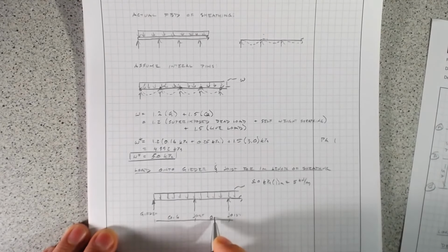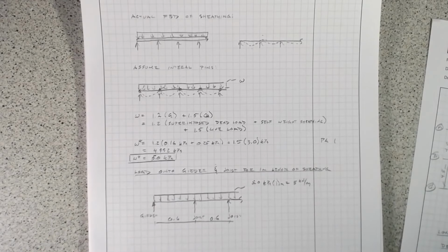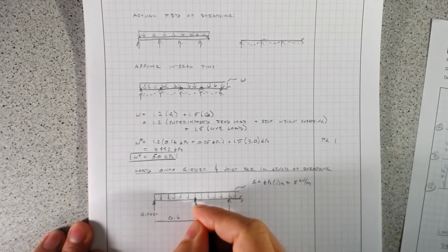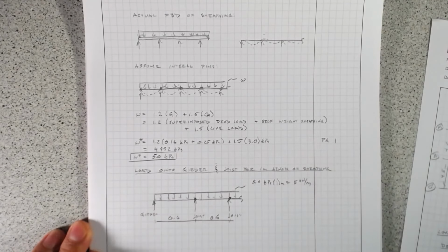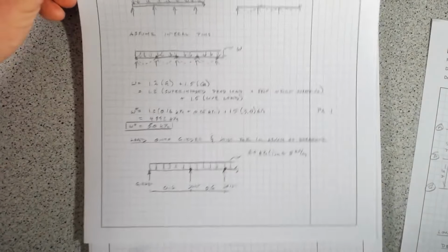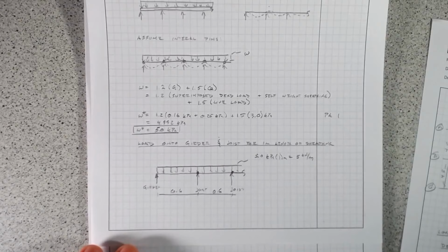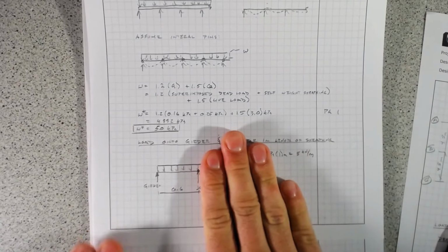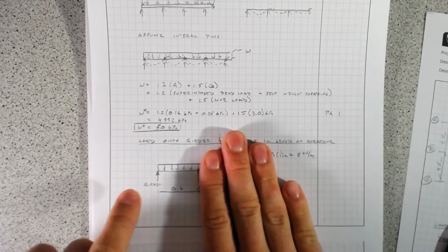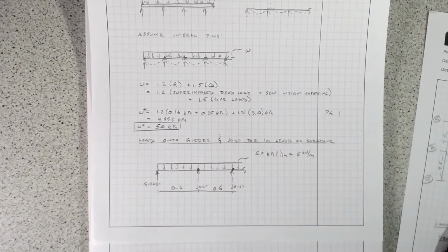And the spacing here, 0.6. All right, well, if I want to find out what the reaction is on this girder, and remember, we're just going to assume internal hinges above each of these so that you can treat this like a simply supported structure. Well, if we're looking at the girder as a simply supported structure, that means that we have a free body diagram just like this. So a uniform load on a simply supported beam. We know that the reactions are just going to be the total load divided by 2. So that's a pretty straightforward